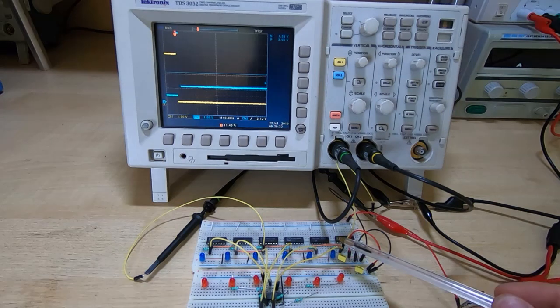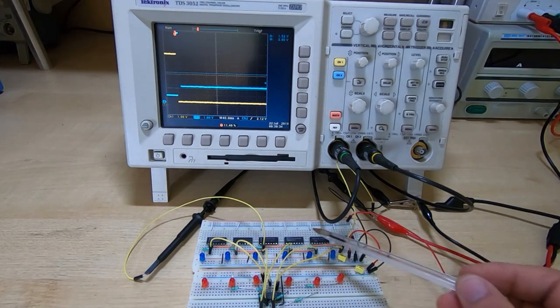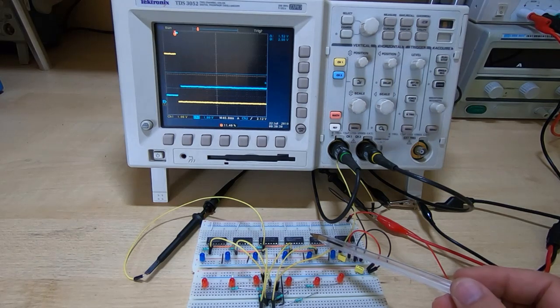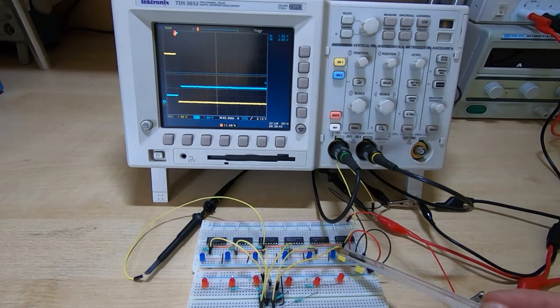The outputs of those 4 devices, they're all 7404s, and the output of the gate that I'm looking at is connected through a resistor to an LED, and the resistor value is chosen such that we're effectively loading it up to about 5 fan-out gate arrangements.